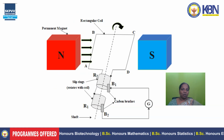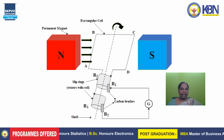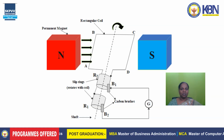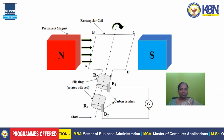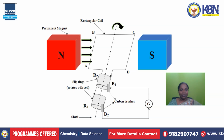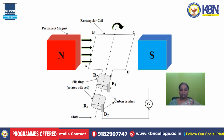So, this is the construction of the AC generator. It is mainly constructed with four parts. Those are the armature and the magnetic field that has been developed with two different poles of magnets, north and south pole. The armature is fitted in between those two poles, and the armature has an individual connection with the two slip rings S1 and S2. They are mobile bodies, and there are fixed bodies on the slip rings. Those are brushes. They are made of carbon material, and the final output from the AC generator is collected through the brushes.